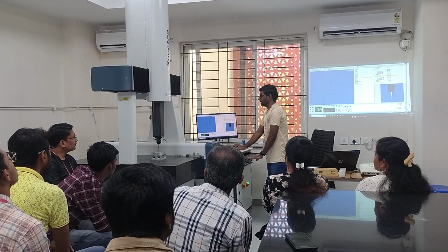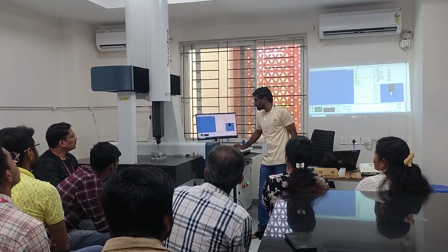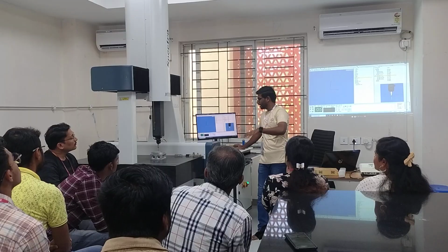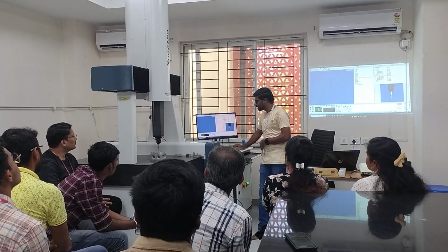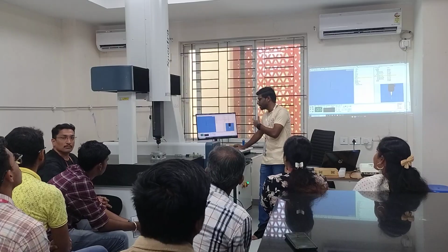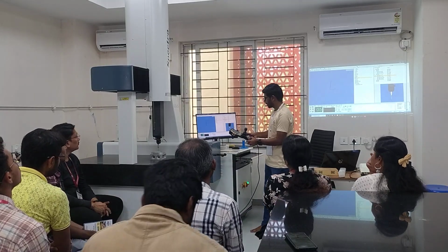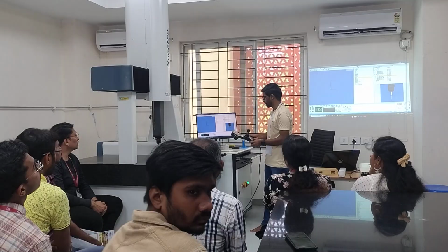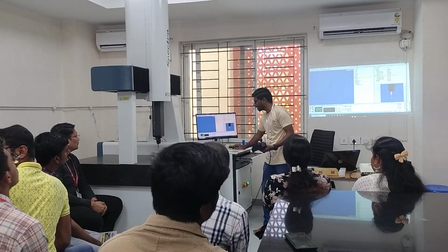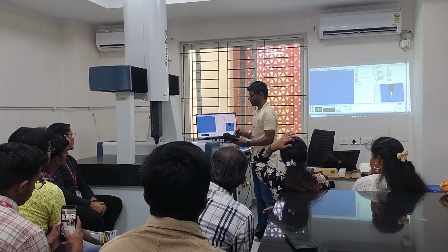I'm sorry, I have made a mistake. I have taken 5 points, but I have not selected a plane here. I'm supposed to measure a plane, right? So what kind of object or form you are going to measure has to be selected. Definitely I'll have to cancel all of them. So I'll select plane here because I'm going to measure a plane. Then again I'll have to take 5 points.